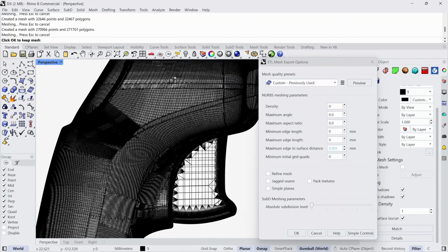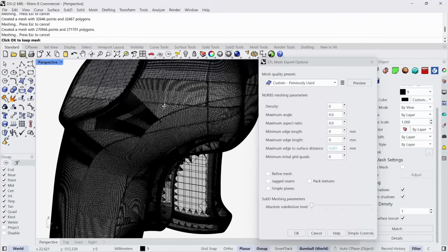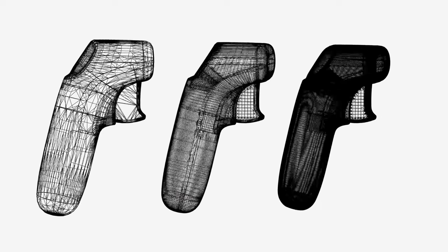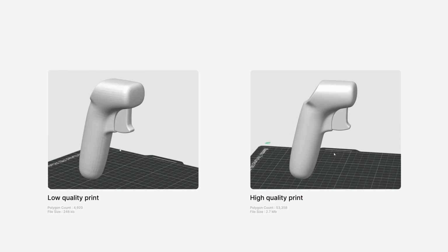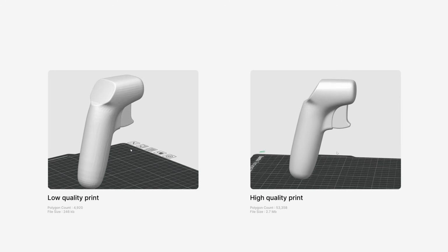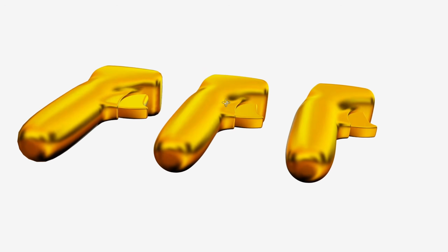See the difference? The mesh is now dense and follows the surface curvature perfectly. This process is similar in other CAD packages like Fusion or SolidWorks. When exporting, instead of low or medium settings, use the custom setting to dial in these parameters. The logic remains the same across all major CAD packages.